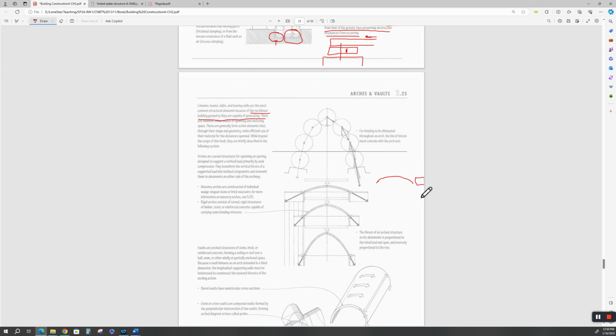Well, that's no different than an arch. So when they put the load on the truck, this thing is already bowed up. Then it flattens out when you load it down. So it's pre-cambered, which resists the load. If you didn't do that, then you'd have something like this, which would be bad.